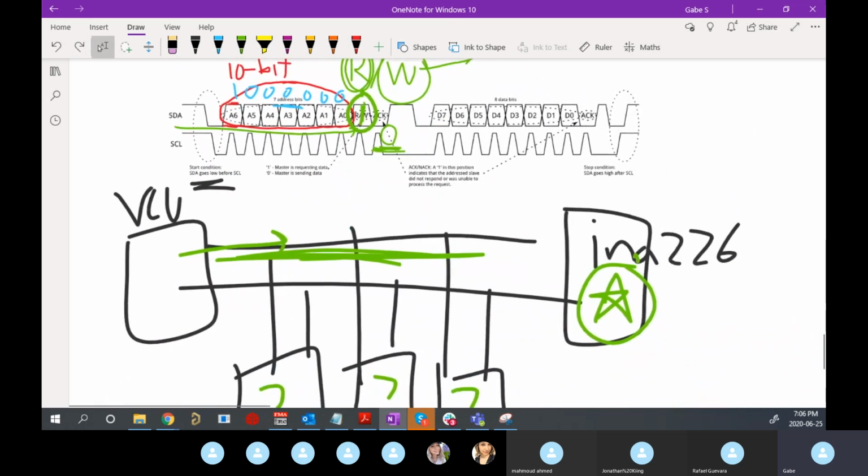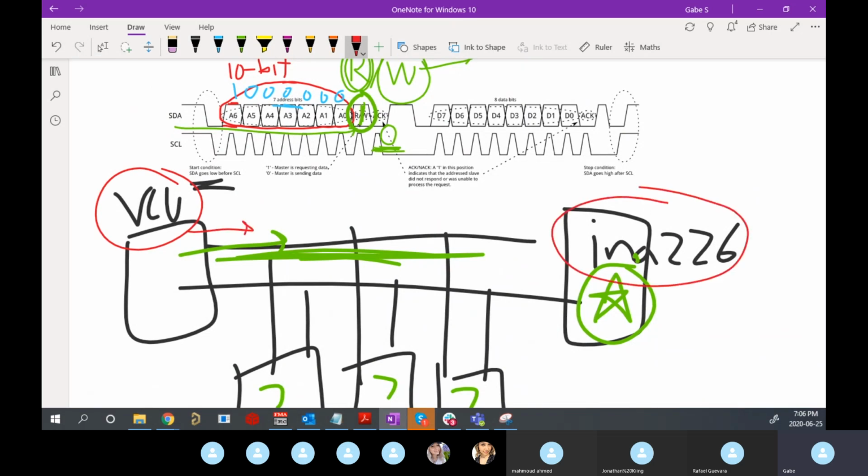So what did we say? We said, I'm master. I'm going to say what address I want to talk to. So I said, okay, I want to talk to the INA226. I want to talk to my current sensor. What's up, bro? I have your address. I'm going to call you. INA226, I want to write to you. So I would say 1000000, right?